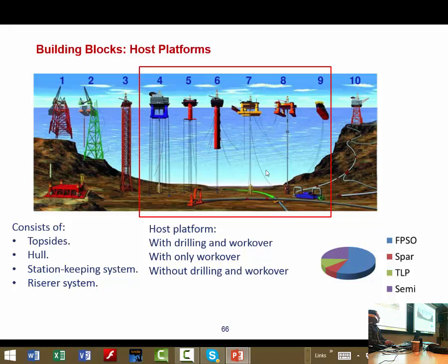Legally, if the well goes all the way to the platform and you get a hole in the riser, the well goes to the sky. But at least for the projects which I have been working on up to now, we always had one valve, even when we have a dry tree on the system. We had one valve at the wellhead. So basically the well ended in the seabed. You can always close it there. The riser, it's okay, but you get the hole, you get the break.